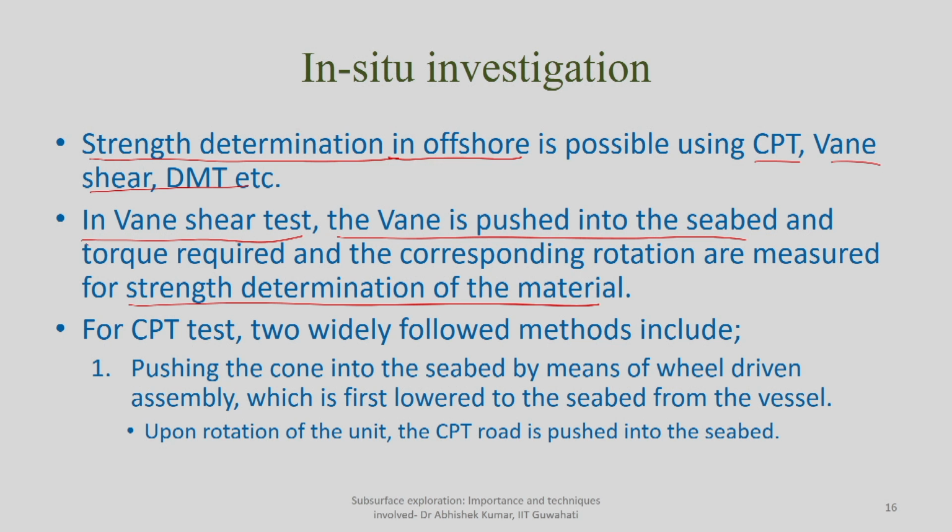And at times, if you have some kind of transducer behind the cone tip, it can also be used for determination of pore water pressure. That arrangement is also possible and practiced in many of the setups. So, this CPT test consists of 2 to 3 kinds of typical readings, and as we mentioned, CPT, unlike other methods, gives you a continuous profile in terms of cone tip resistance, in terms of skin friction or pore water pressure. So, this is the advantage. Only thing, in case of CPT you do not get any sample.